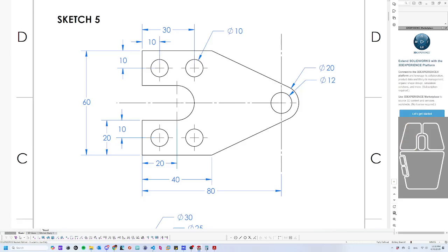So I said around the center point, I'm going to put the circle, and then I'm going to put an arc. I'm going to pick center point arc because I know where the center of the arc is supposed to be. Since I'm just doing the general form, I'm going to make sure that I don't have any extra of these dotted lines. I'm just going to start over here and then put the endpoint around there. Okay, I'm going to zoom out and then zoom in on the left so I have some more space to work with.